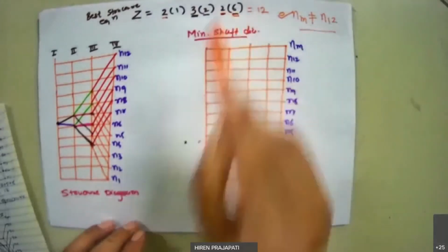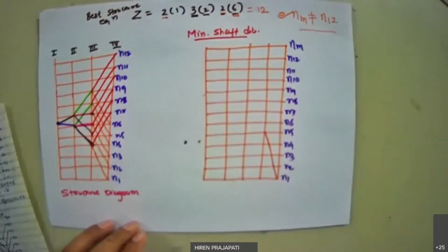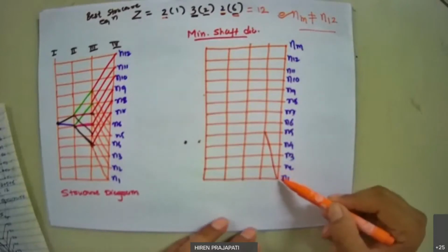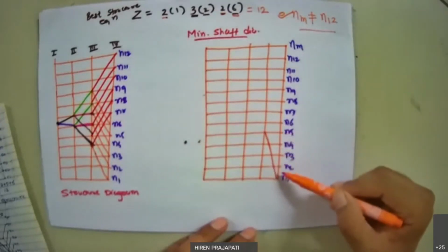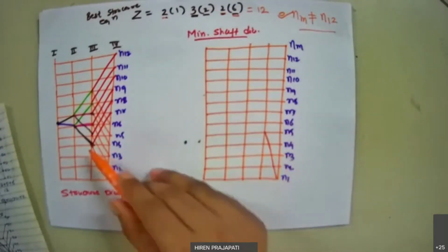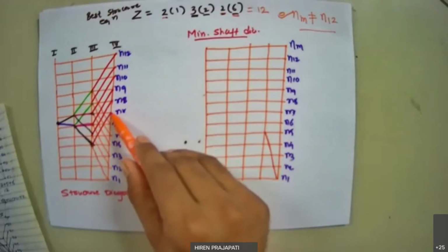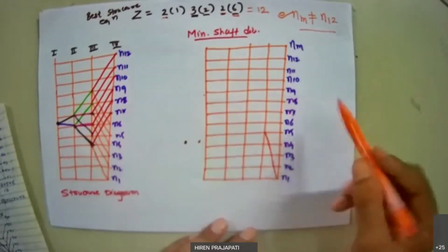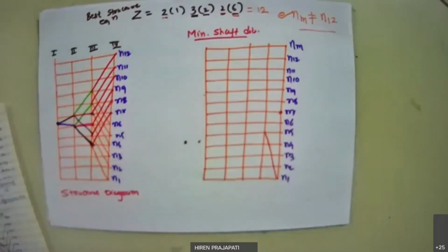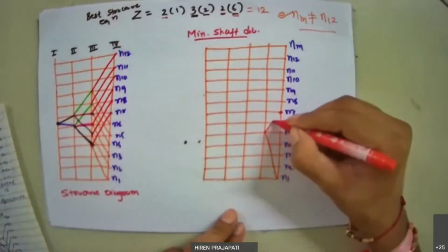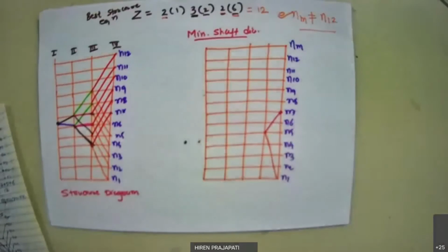The group characteristic number for the last stage is 6. So this is N1, the minimum RPM available. Then the maximum RPM should be with progression 6, which is N7. So N7 is here. I need to connect N7 with N5, right?